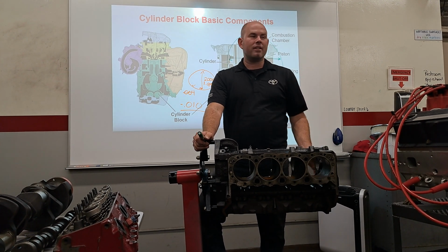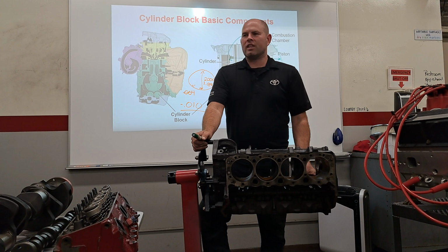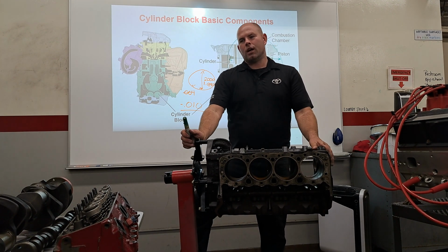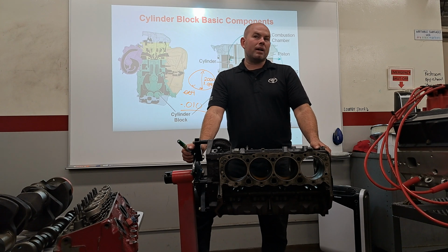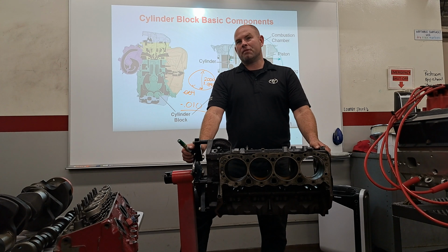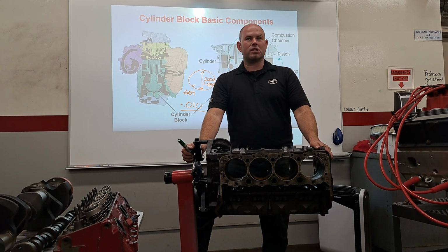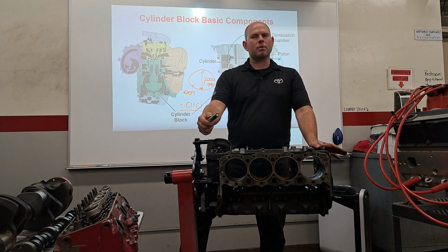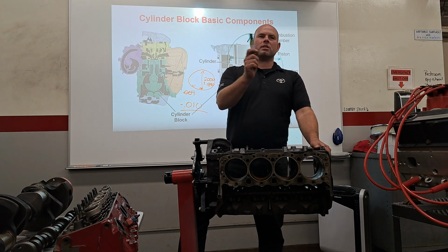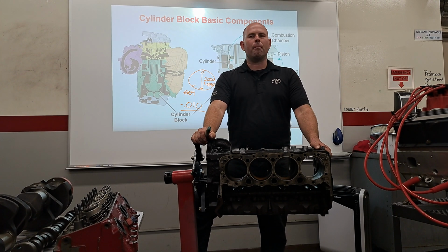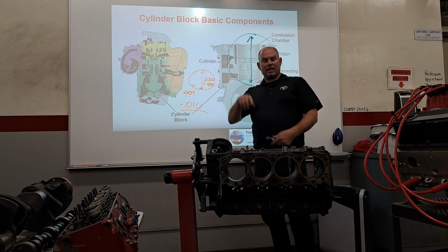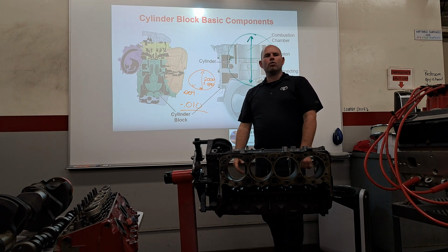So I bought this car, whatever, and the guy rebuilt the engine and everything's all good, but it burns oil. Well, they might have rebuilt the engine, but if it's burning oil, it really probably is coming from inside the engine because that's where it lives. So something's wrong there. Now, one of the cars was turbo. Possibility it could be turbo seals, these types of things. There's a possibility it could be a problem with the PCV system, but there's also a possibility that it had an out-of-round cylinder and they just put new rings in there. New rings don't seal an out-of-round cylinder.